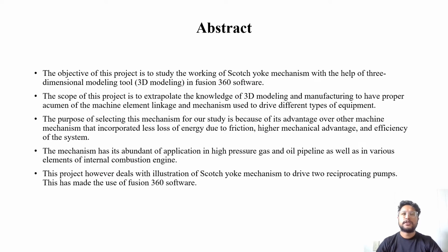For the abstract of this project, the Scotch yoke, also known as the slotted link mechanism, is a reciprocating motion mechanism converting the linear motion of the slider into rotational motion or vice versa. The piston or the other reciprocating part is directly coupled to a sliding yoke with a slot that engages a pin on the rotating part. The location of the piston versus the time is simple harmonic motion, which means a sine wave having constant amplitude and constant frequency given at a constant rotational speed.